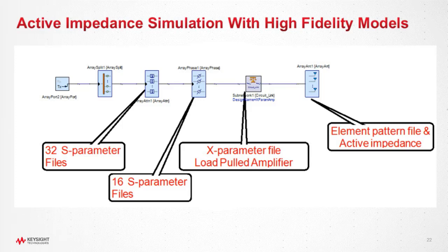One peculiar characteristic of phased arrays is that as we scan the beam, the impedance looking into each one of these elements changes. This changing beam impedance or changing element impedance will impact the performance of the amplifier if the amplifier model can behave based on the load to which it is connected.